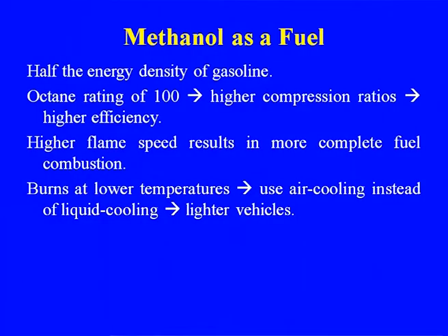Methanol as a fuel: I already discussed the importance of oxygenates in module 6. You see methanol as a fuel has an energy density comparable to gasoline, an octane rating of 100, higher compression ratio, higher efficiency, and higher flame speed, which results in more complete fuel combustion. It burns at a lower temperature, uses air cooling instead of liquid cooling, and allows lighter vehicles. These are some of the advantages of methanol, and why methanol is being preferred as an oxygenate in fuel.